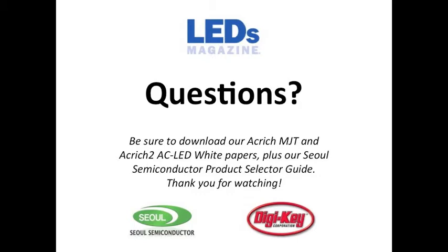Right. So actually in some of the product information, the white papers that you have access to right now, it talks a lot more in detail about how the IC operates. Specifically, the latest one is what we call a 4-step IC. If you're operating at 120 volts, you have a step at 30 volts, a step at 60 volts, a step at 90, a step at 120. It's actually a little bit less than that because the LEDs are going to turn on before that. It just makes it easier for calculations.